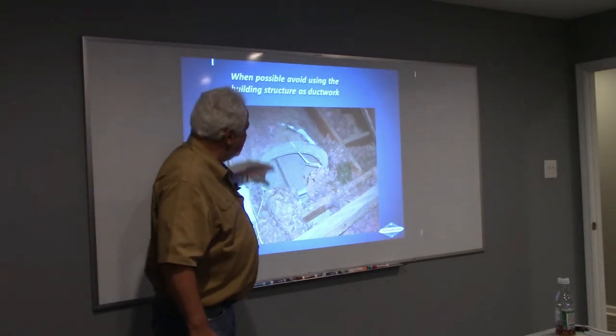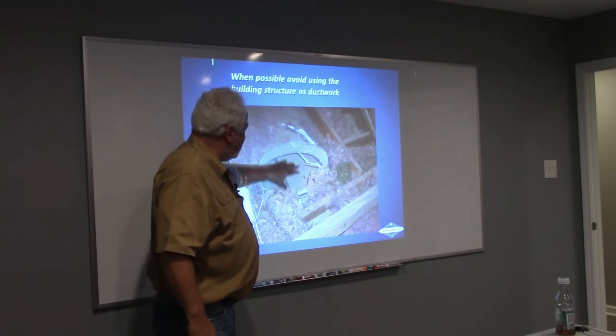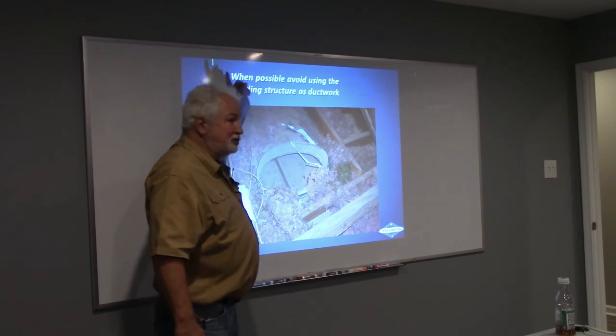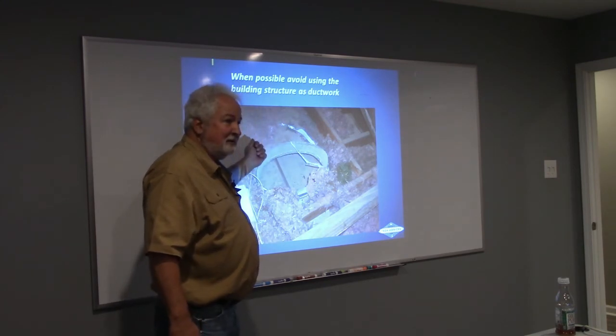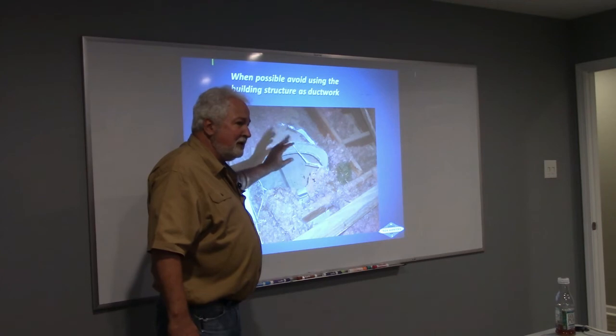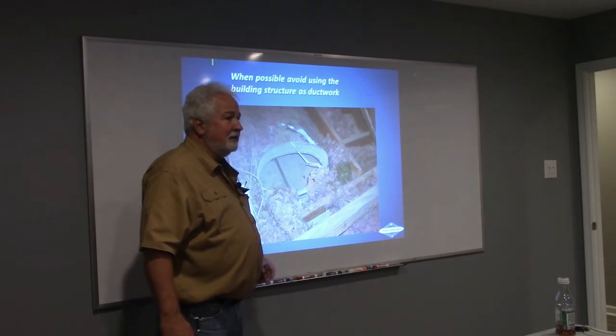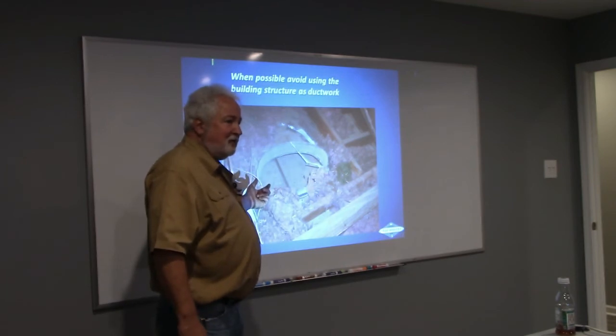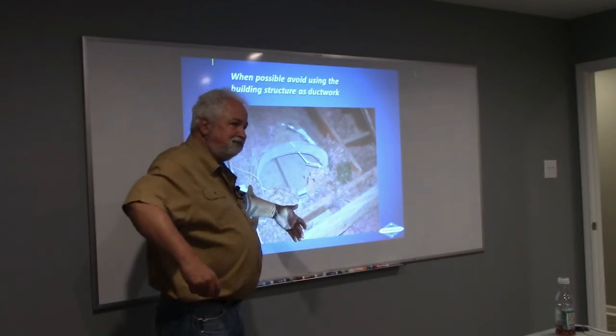So look, if you put that collar on top of this sheetrock and you try and get, what are you going to get? I mean, are all those joists all sealed all the way down? No, you're going to suck dust and mold and dirt and everything everywhere, because it's going to pull from everywhere. So if I've got return air leaks all over the place, the home's going to go positive.